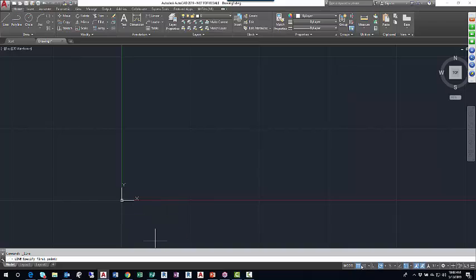I can actually cheat and turn on my snap function. There we go. With the snap function showing, you can probably see the coordinates pretty small, but I'm at a coordinate right now of 0, 0. If I move away from that diagonally, I'm at -5, -5, a little further, -1, -1. So the coordinates are positive, moving up and right from your UCS icon, and negative, moving down and left.